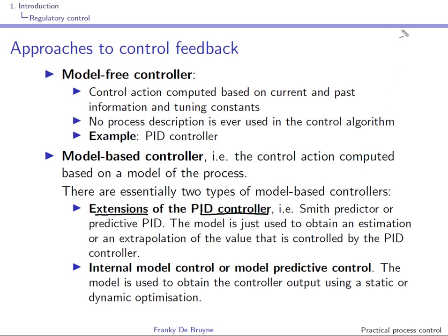So you can draw things as follows. You have the PI or PID controller. This is the set point, and what enters over here is the prediction, a prediction in the future, an anticipation, and this anticipation is constructed from a model.